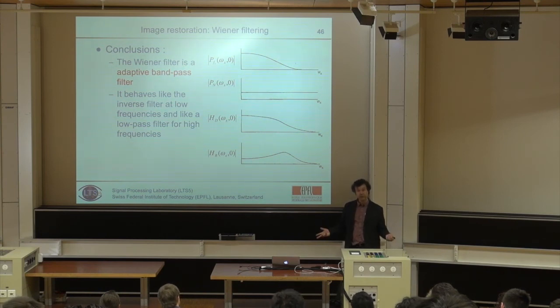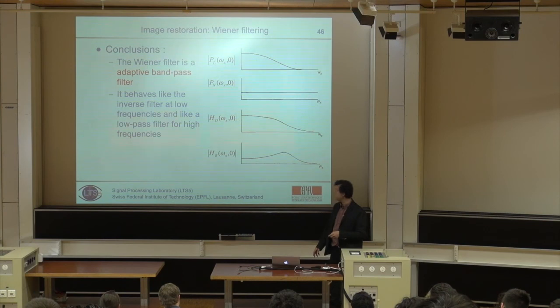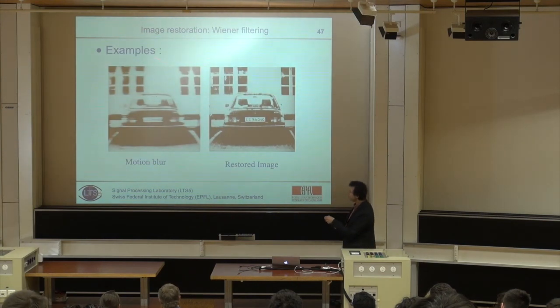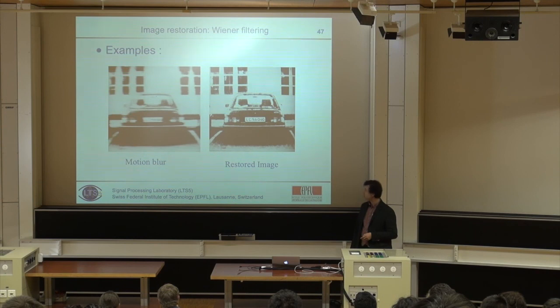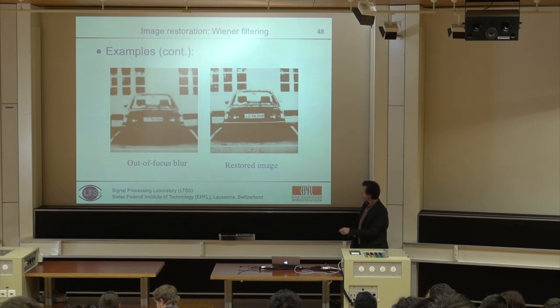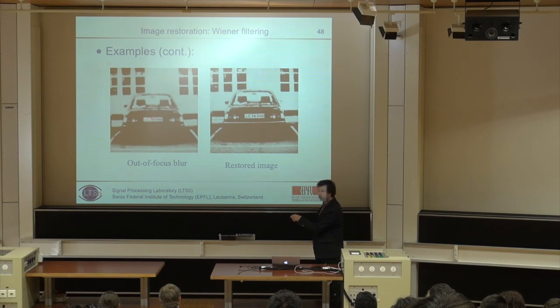And that's really the Wiener filter. And it works increasingly well, impressively well. Look at this blurred and degraded image. After restoration, you get that. These are very crappy images, but you still get very nice results. This is blurred, and you can restore. The content is still there, but it's blurred. You undo it while controlling the noise.